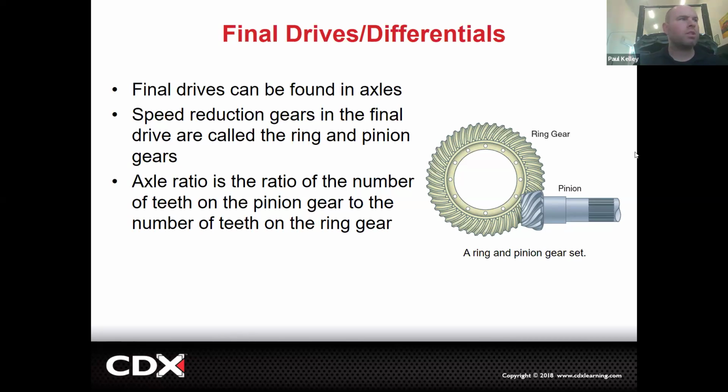Now, in a transaxle, we do have a ring and pinion, but they're typically not this hypoid design, although they used to look like this. These teeth are kind of unique. So we talked a bit about this in the previous unit too, because we looked at straight cut spur gears, or we looked at helical cut gears kind of with the angle. Well, hypoid is not only angled, if you look, they're curved. They're full on curved.